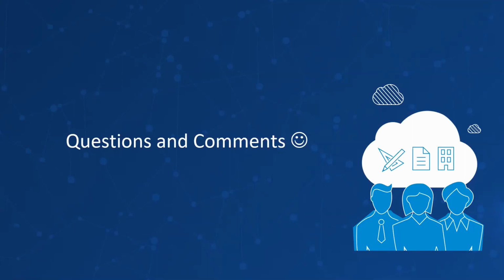Okay, so what are the solutions that we can do? In BIM 360, there's what you call permissioning. As Jello discussed a while ago, only certain people can access a certain folder. You need that kind of security and permission so that people won't carelessly rename or move the file. There are access levels wherein you cannot rename or move folders.